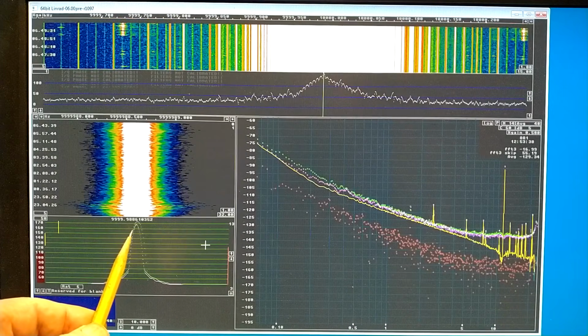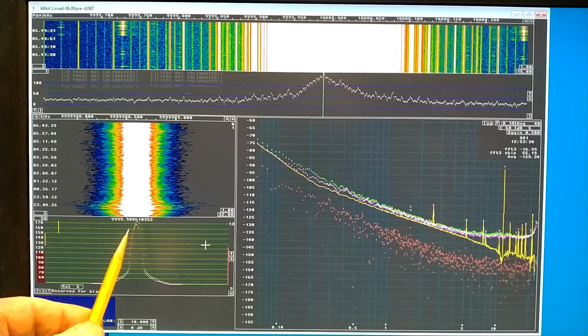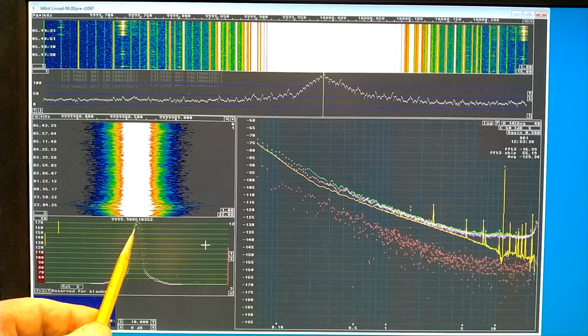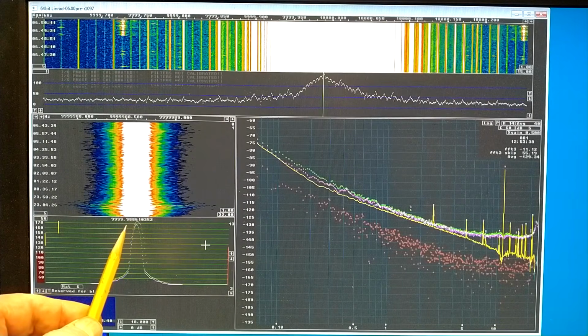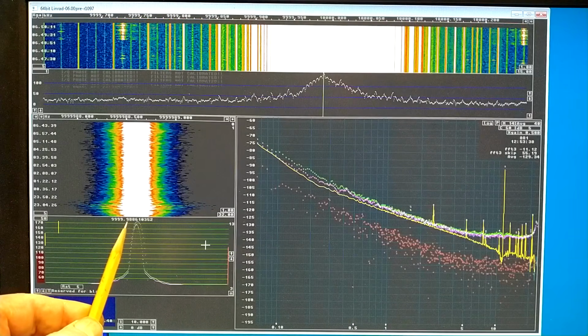So what I do is I take that complex function and do the Fourier transform, remove the DC component by shifting the phase accordingly, and then I have AM and FM modulation on the signal.